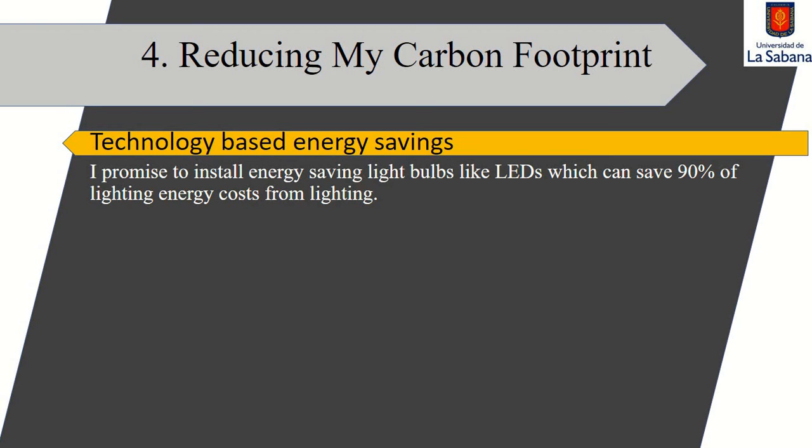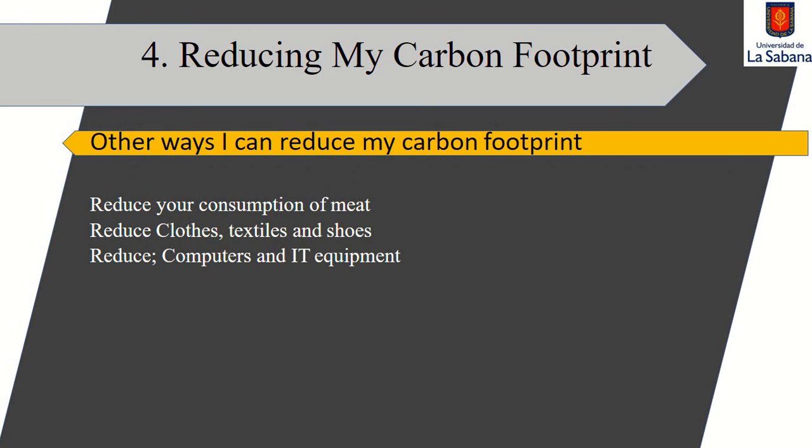According to Endesa and company, approximately 20% of the electrical consumption of your home corresponds to lighting. Therefore, 20% of the current consumption that corresponds to lighting must be calculated, and from that result, the 90% that corresponds to energy savings due to LEDs is subtracted. The annual consumption of light will be 998 kilowatt hours.